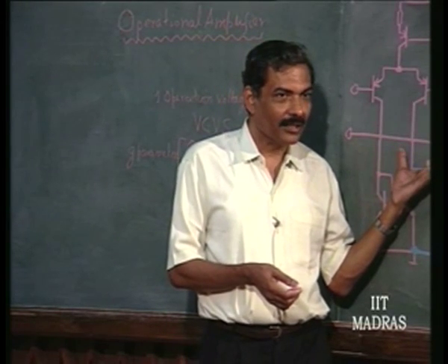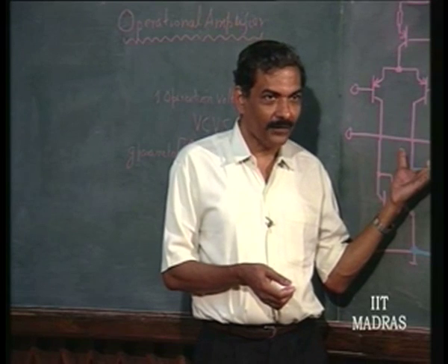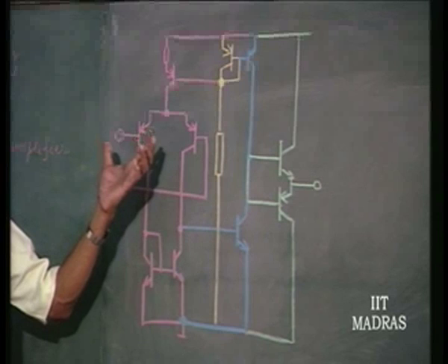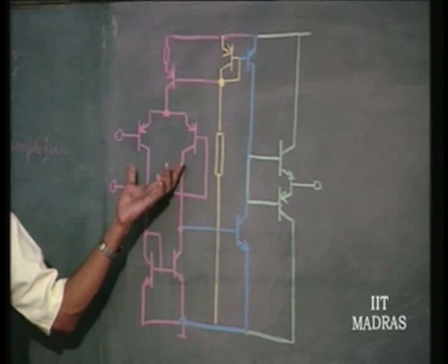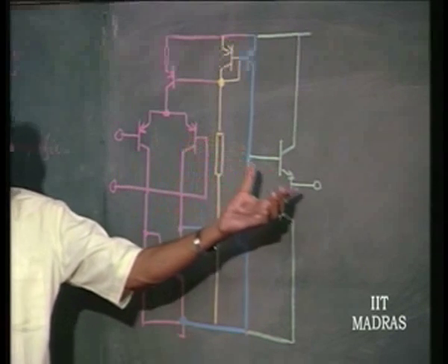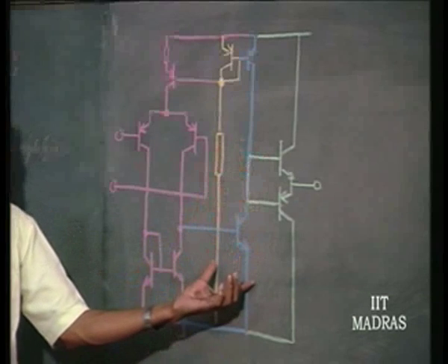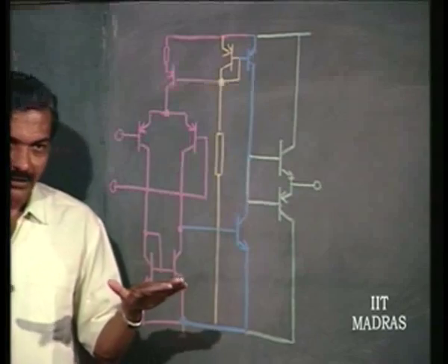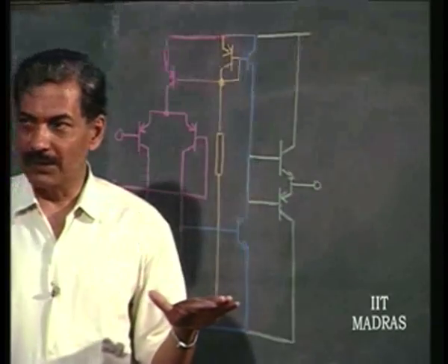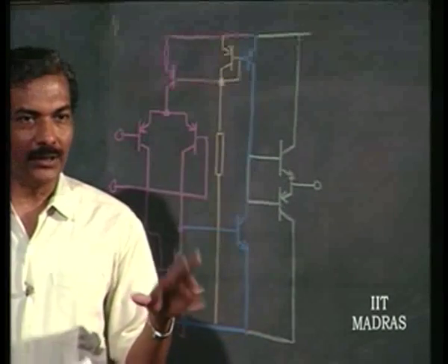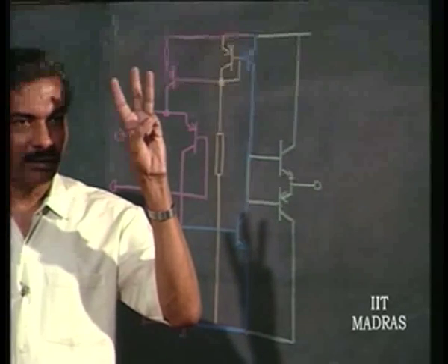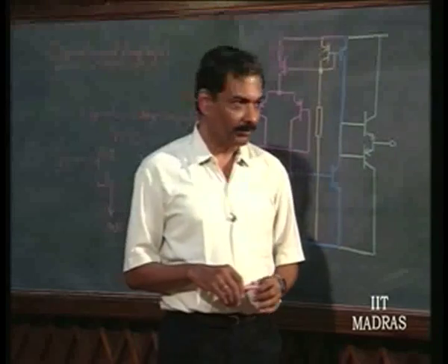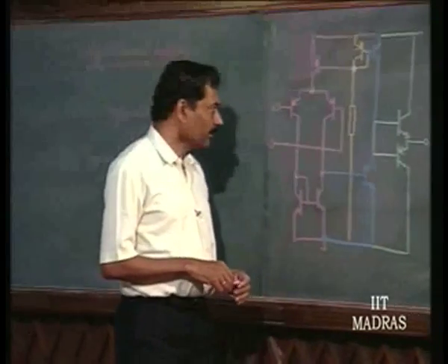This kind of thing had to be got rid of, and therefore, people then said we will give the responsibility of the input to the input stage, responsibility of the output to the output stage, and the gain to the intermediate stage, thereby freezing the number of stages of most present day op amps into 3 stages. We will discuss further about this op amp in the next class.